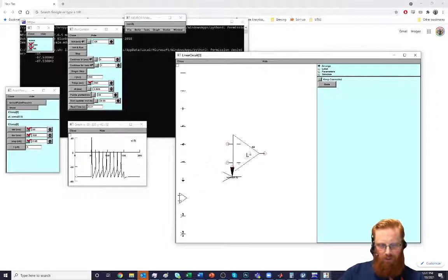And then the first thing we're probably going to want to put in is an op amp that always comes out massive, and you can shrink it a little bit and make your life a little bit easier. Because typically, if you've had to resort to this, you're going to be building a moderately complex circuit, and you want as much space as you can. So just to prove that things are vaguely working, we're just going to create a voltage follower amp or a buffer amplifier, right? So it's just going to be the voltage out of the amplifier is equal to the voltage into the cell, right?